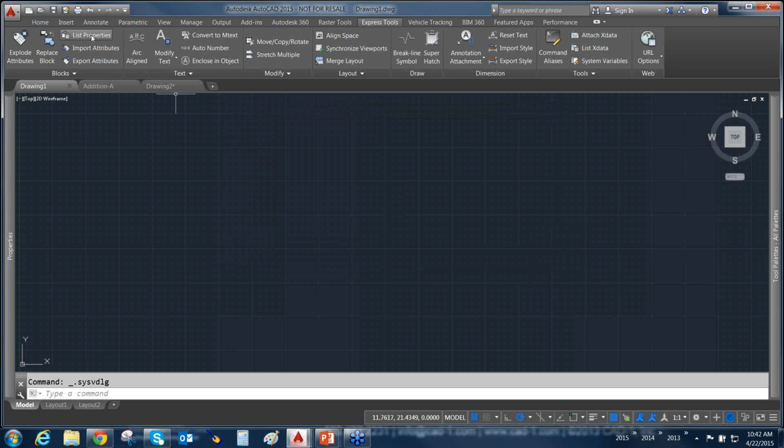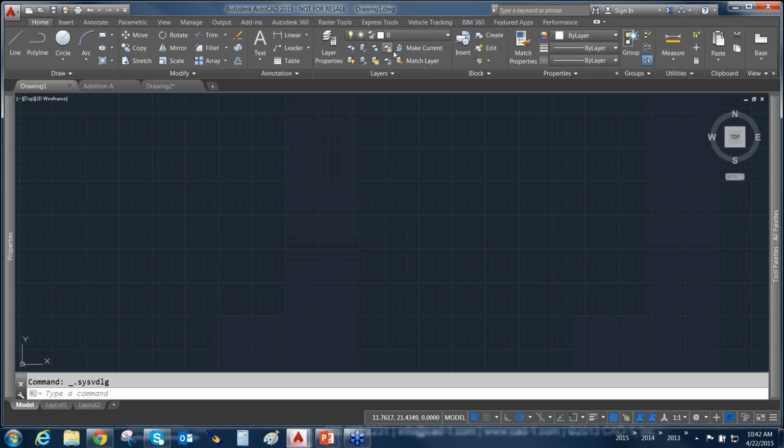And that will not bring any corruptions, errors, or anything else. Now, as far as layers go, there are tools out there for exporting and importing layers, but you don't need to do this. Settings would be the only thing that you'd want to export and import. Now, for those of you, unfortunately, who have AutoCAD LT and you don't have those tools, you're going to be doing a lot of typing. I'm sorry, that's the thing about AutoCAD LT, limited technology, no automation. If you want the automation, you're going to have to get one of the updated or upgraded products.